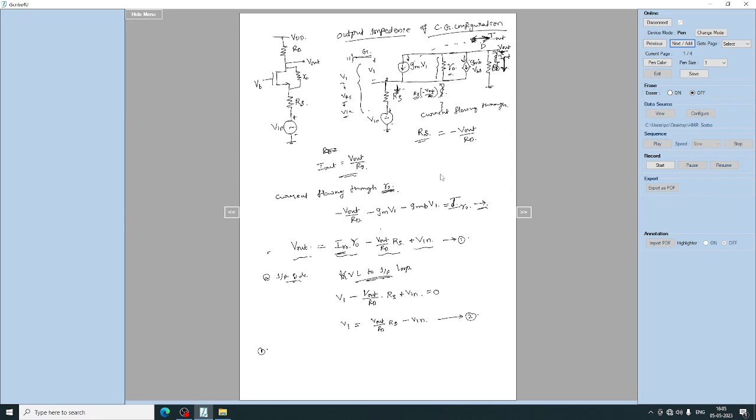So V out is equal to I out into R naught, R naught into I R naught. What is I R naught? I R naught is this, minus V out by RD.